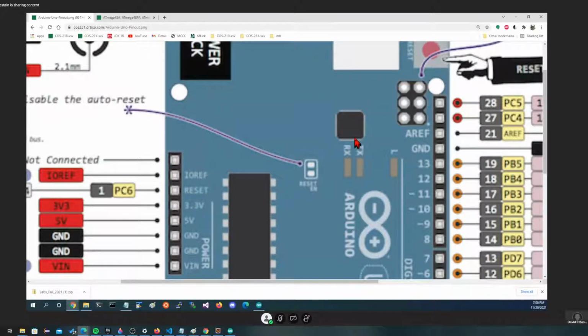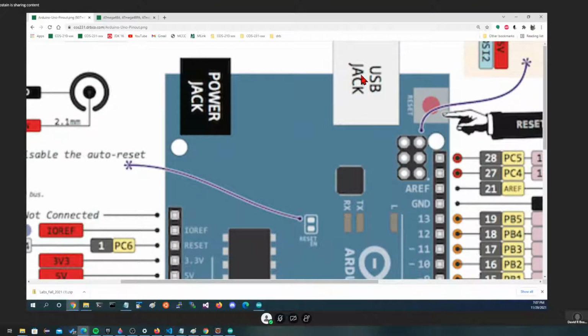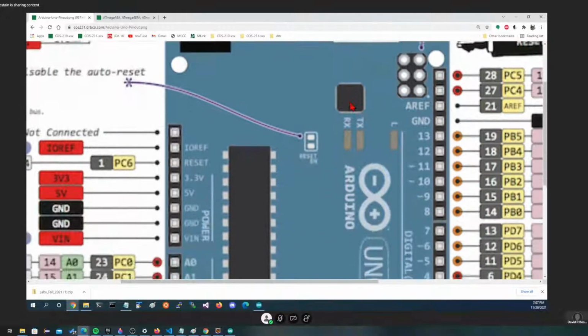And as every bit is transmitted, we'll see a byte be transmitted. It'll light up. This then converts it into USB, which sends it out the USB port through the USB cable over to our PC, where we'll have to have a program running that can read the USB. Well, the USB actually makes it look like it's RS-232 data. So as long as we can read RS-232 data, then we're able to read the USB stuff that was sent to us. And hopefully then we'll make up some way to print it on our screen.